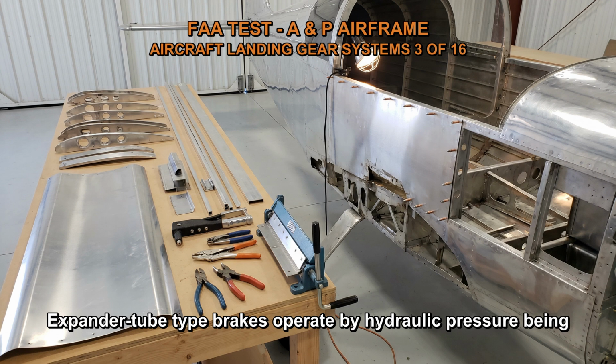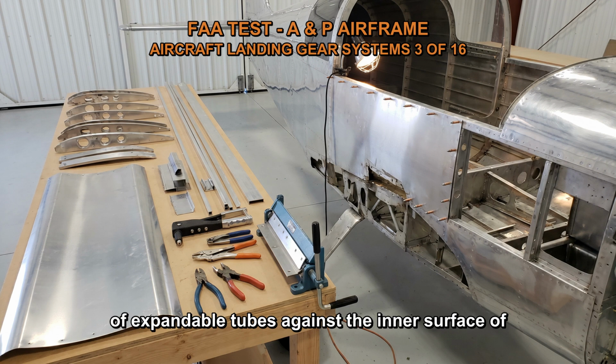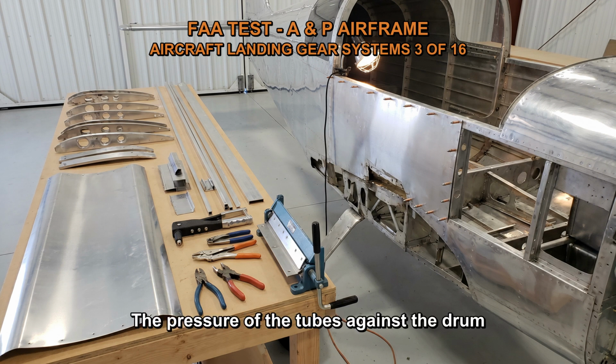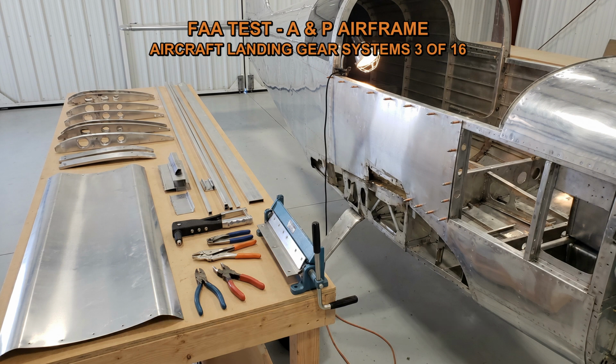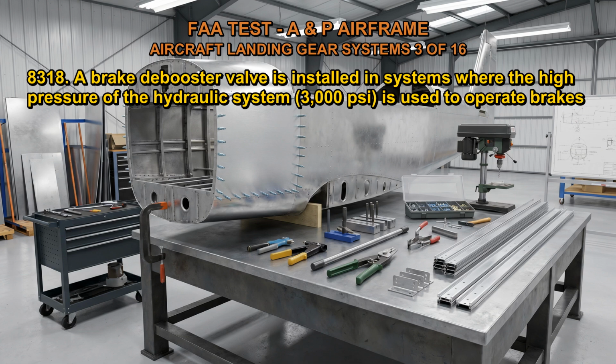Expander tube type brakes operate by hydraulic pressure being applied to a piston, which pushes a set of expandable tubes against the inner surface of the brake drum. The pressure of the tubes against the drum creates the braking force. This type of brake relies on hydraulic pressure to expand the tubes, and therefore cannot be adapted for mechanical operation.